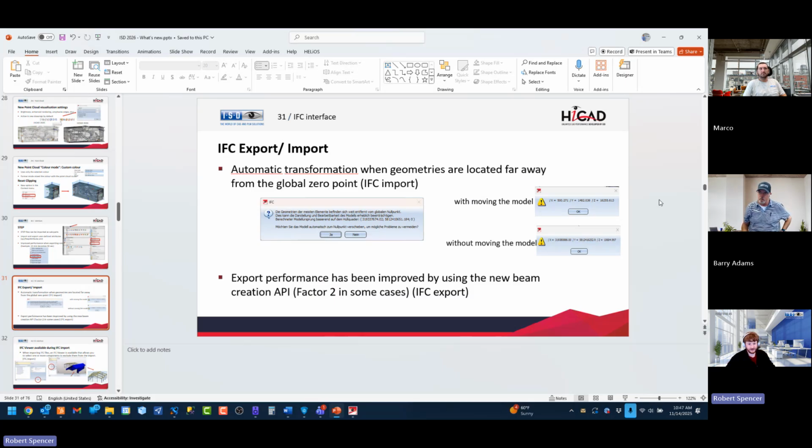We're working on a direct .rvt conversion, which in my opinion, okay, that's great. That's more for marketing, because we can do everything right now with IFC, but for some reason it's like pulling teeth to make people understand that all you have to do is take your Revit model and say save as IFC and send it on over.